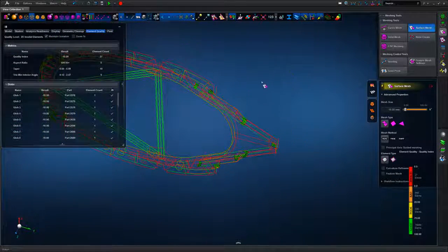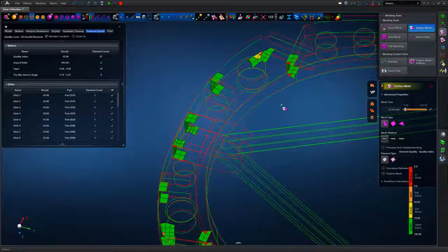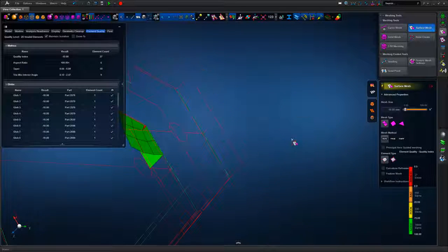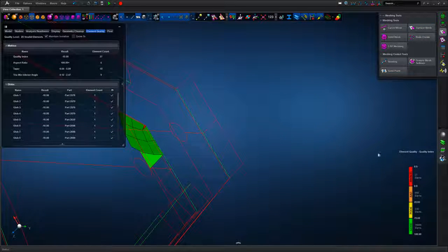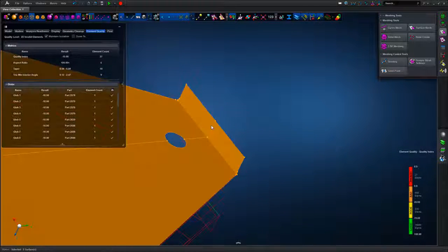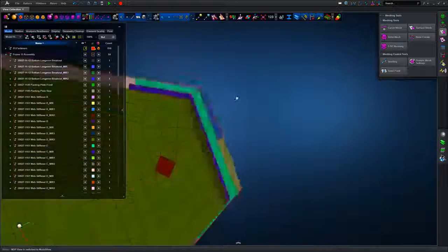of the model where we have poor element quality, such as the element quality check is showing that has failed. So we would not be able to run an analysis with such skewed or highly irregular elements. So it's a case of looking through the model and understanding where those poorly defined elements are, and usually it's a function of bad geometry or overextended mid-surfaces, that type of thing.